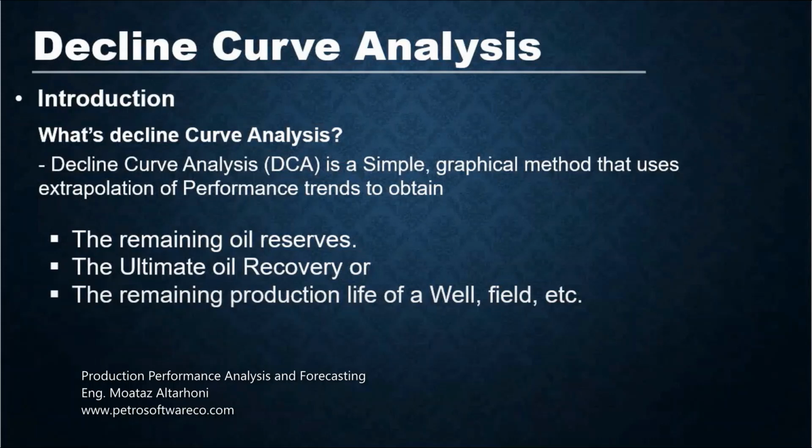We know the volumetric equation, used initially in the reservoir, determines how much hydrocarbon is in the reservoir. Then with time, after we start the production, we can use a different method called the material balance equation. This is a very powerful method that helps us determine the hydrocarbon in place, and we can also use it to predict the water influx. Then we can predict the production in the future.